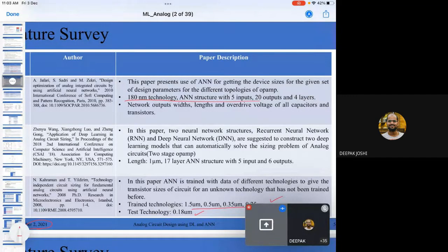Now let us select one technology first. In that technology, by using ngspice or LTspice, you can find out a variety of data. How can it be found? You tweak the W/L ratio, you fix the VDD, and you can find a set of outputs. Similarly, on a different technology, we can have the same tweaking and generate a set of database there. Similarly, on the other technology.